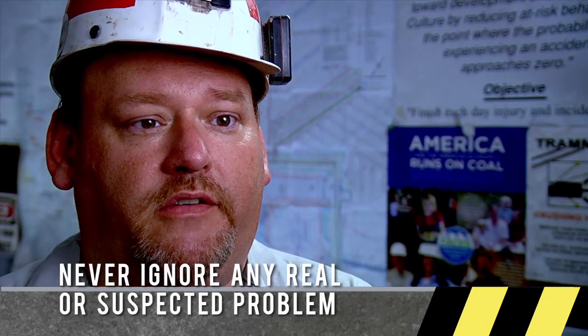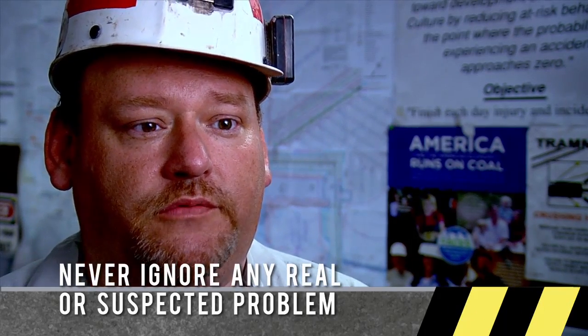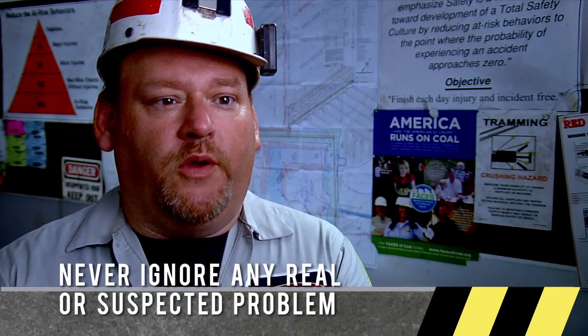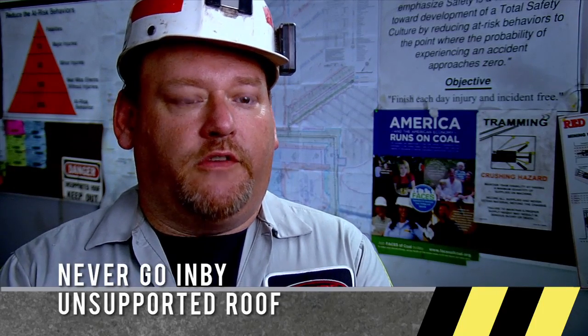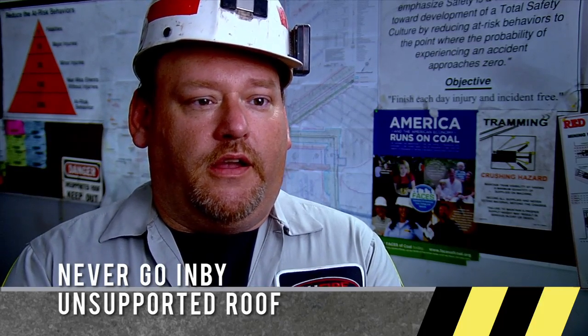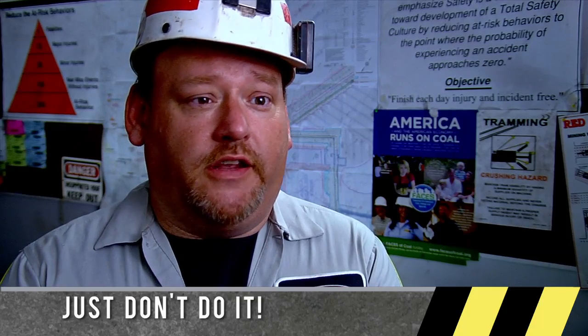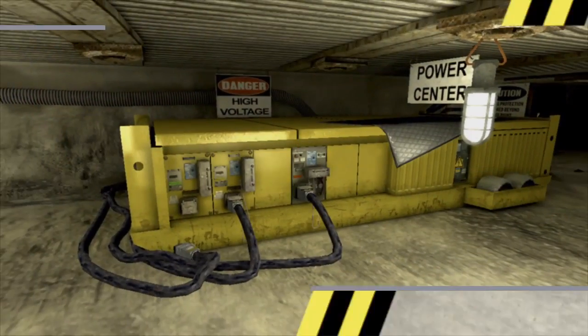If a miner sees or suspects a problem with the roof, he should call someone else's attention to it, possibly a roof bolter, or if they both can't figure out what's wrong with the roof, they need to contact a mine official. A miner should never go beyond supported roof for multiple reasons. There's nothing there to hold the strata. It's against state and federal regulations. It's just unsafe, and we shouldn't do it.